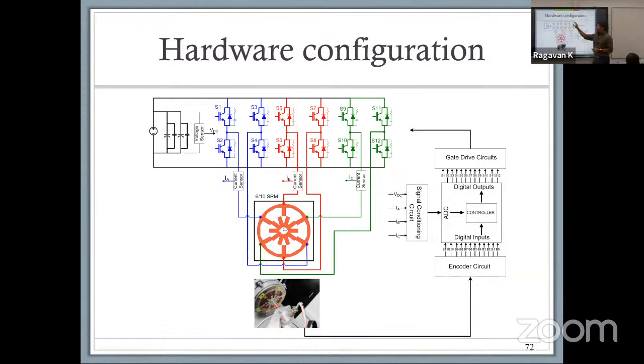The same thing as well, if you're designing a converter that, let's say you have an asymmetric bridge available from before. Great, it gets the job done unless your current sensor is, let's say, designed for 25 amps and you are never going to go above 5 amps. The resolution of a current sensor is going to be filled with noise, right? When you measure it, your resolution of your sensor feedback is going to be very limited.